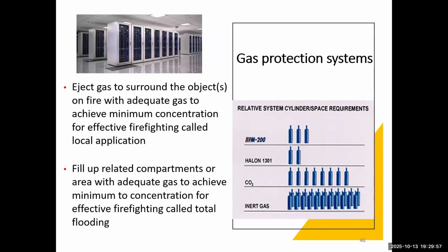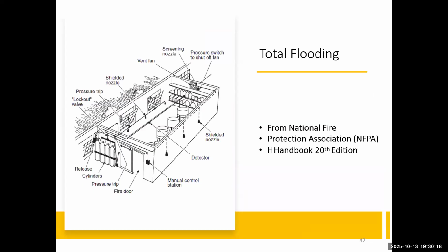So here we need to mention total flooding. Total flooding is that we fill up the related compartments or areas with adequate gas to achieve the minimum concentration for effective firefighting. This behavior we call total flooding. And total flooding is another one we pay attention to.